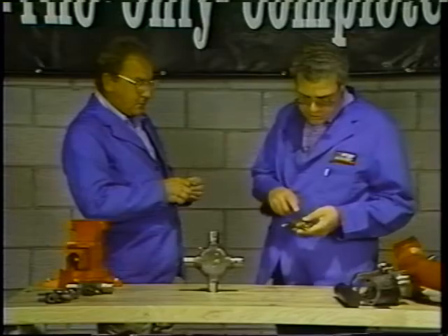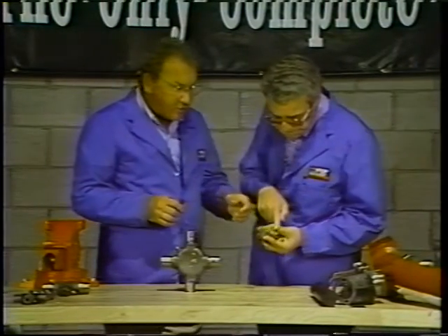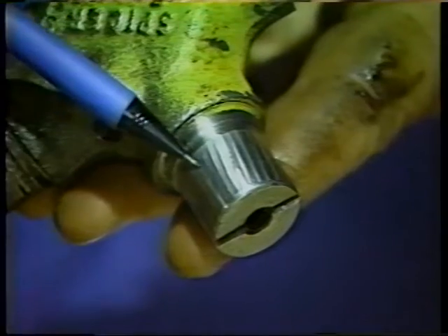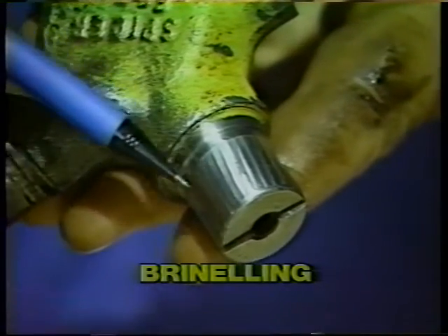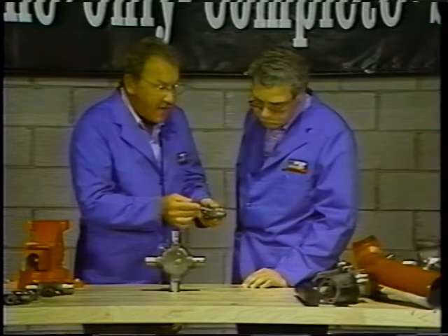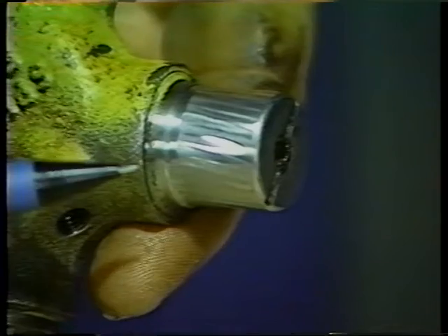And it appears that this U-joint has been worn out too, huh? You're right. This is known as Brinelling. It occurs when the movement of rollers around the trunnion is severely restricted because of super tight bearing caps, excessively high angles or no angle at all, or an out-of-balance drive shaft. Now, Brinelling on the face of the trunnion is caused by a tight spline.